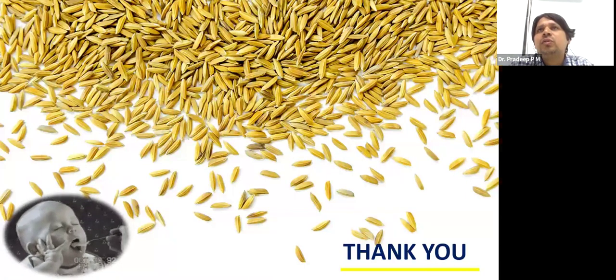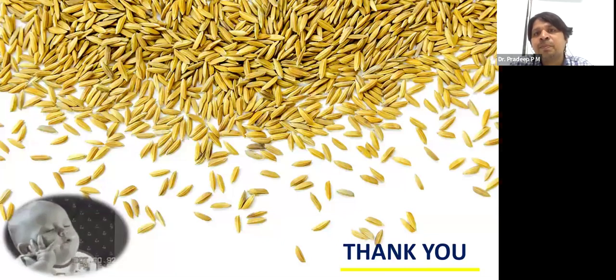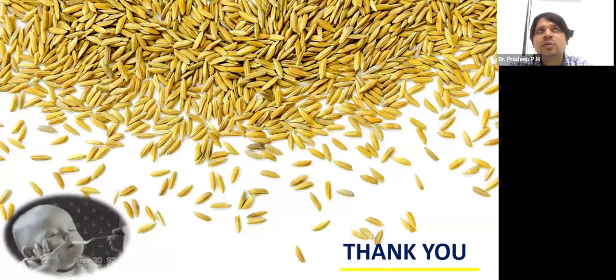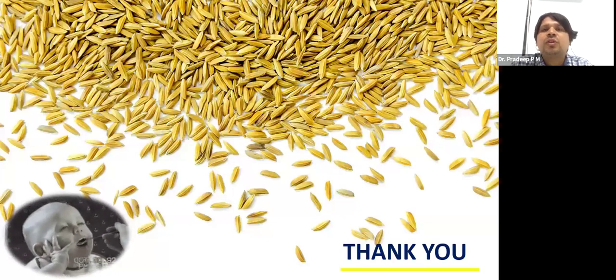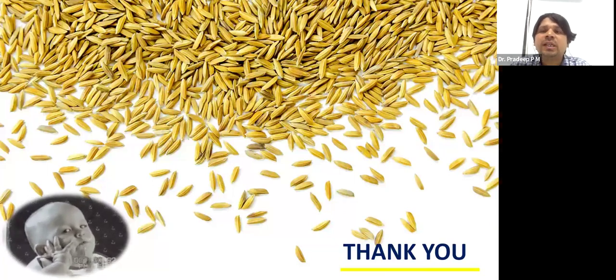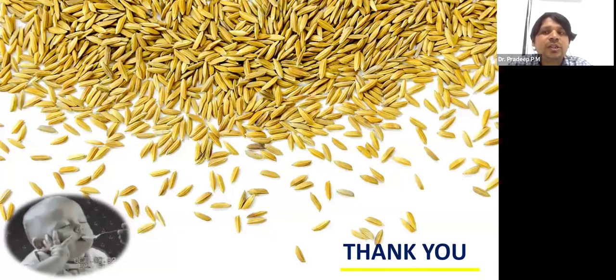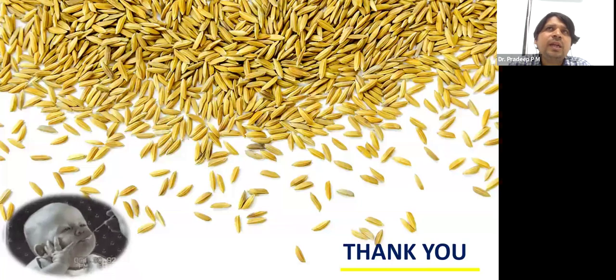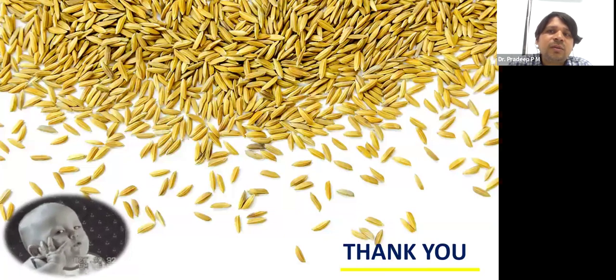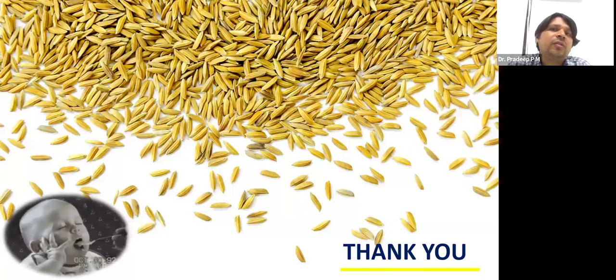And usually what they do, nowadays they store in silos. So here the silo environment is such that it is controlled automatically. That means if the paddy is stored for more period of time, they go for mixing the paddy at regular intervals so that there is no formation of heat inside the basal layer of the storage. So they will overcome by using some of the advanced systems where they can predict the moisture and RH activity of the paddy, and thereby they can give the required solutions.